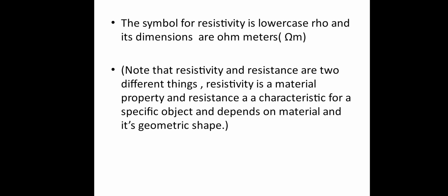The symbol for resistivity is lowercase rho, and its dimension is ohm meters. Note that resistivity and resistance are two different things. Resistivity is a material property, and resistance is a characteristic for a specific object and depends on the material and its geometric shape.